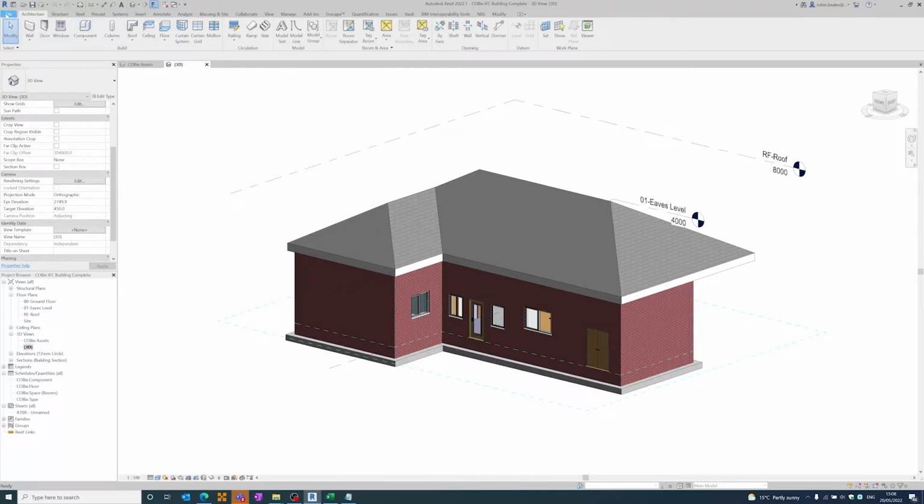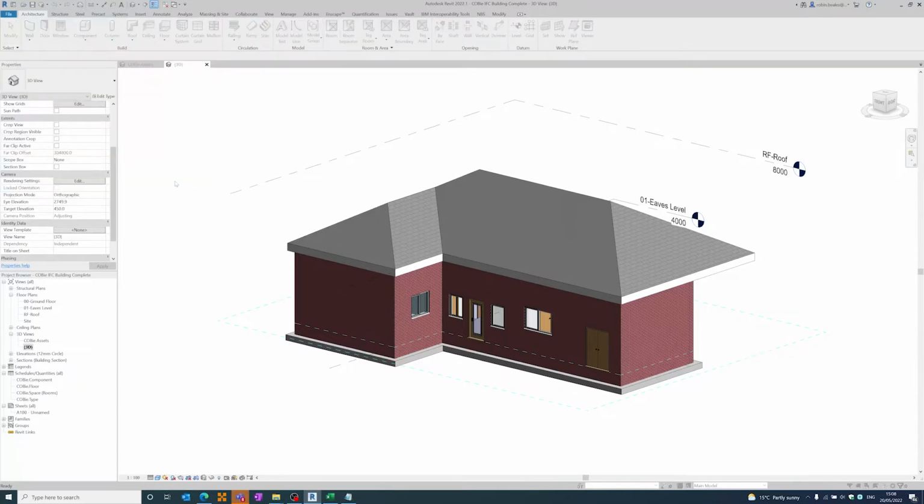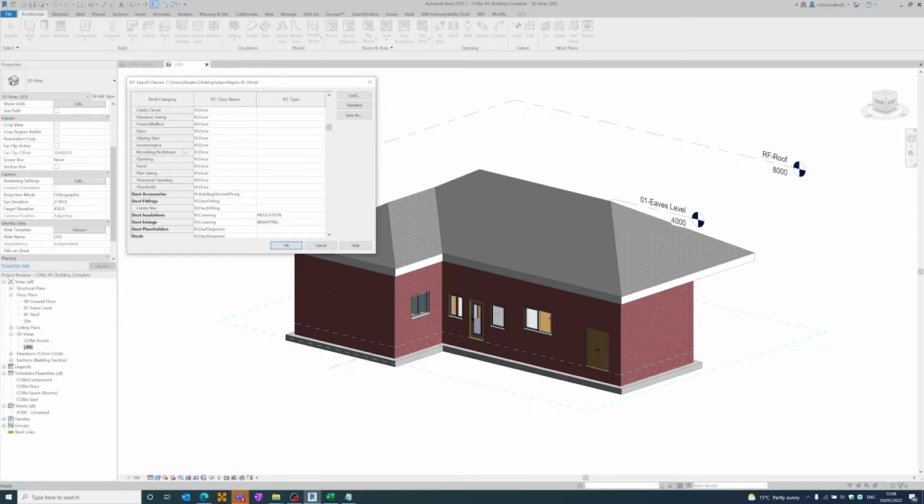However, you will notice that although they have the same IFC class name inside of Revit, they have a very different type name. These have subcategories known in the IFC as enumerations to better define what that component is. Because we're working between multiple different technologies and applications using the IFC, it's important that we have something that fits all. So generally speaking, we have fewer main categories that are then subcategorized within them. This makes the control of information and geometry easier between applications.